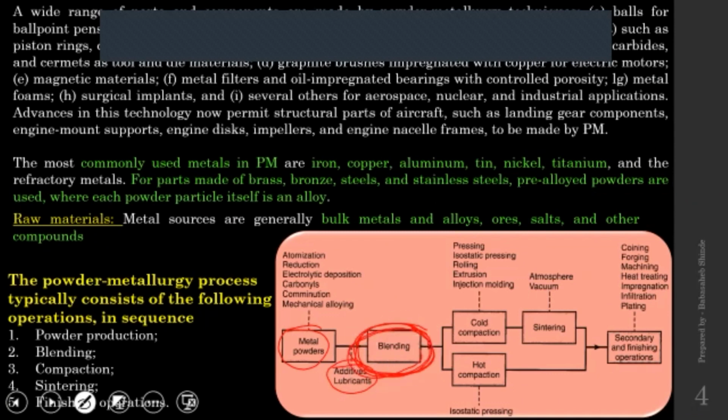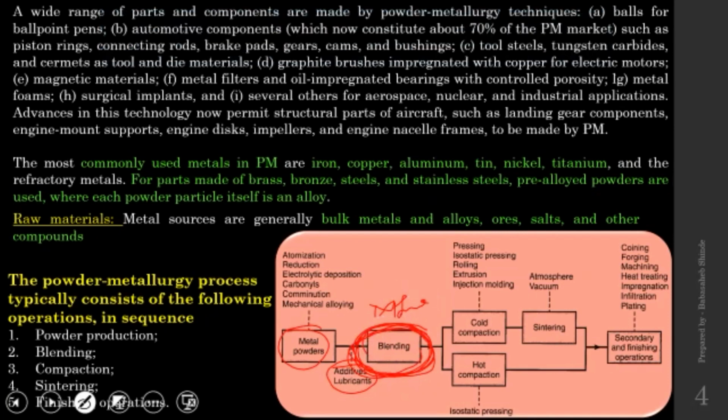And once we have got that mixture, now the next technique is forming a raw or green shape, because this is still at its initial stage. We haven't heated it to its final temperature to get the final characteristics. So it is still in its raw form, and we are offering its shape in its raw form itself. That operation is called compaction.